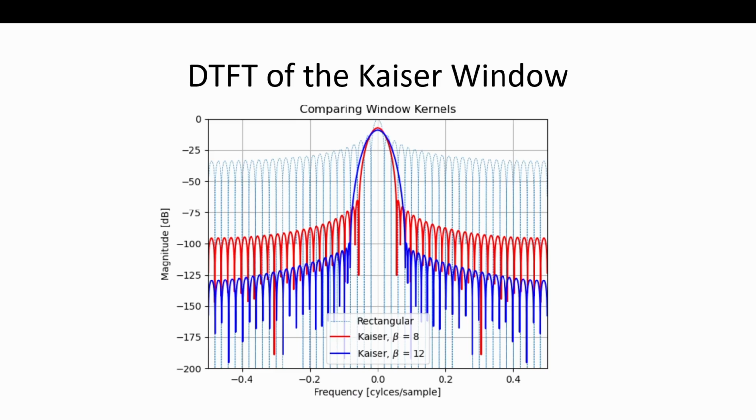So take any of these windows, and we can play with it in Python later. You'll see it. Pass it in, take the FFT, but not just the FFT. Zero pad the heck out of it, and then you'll see this result. And it's telling you everything you need to know. Pretty cool. So you can compare all the windows you want to use, and you can see what the trade is in terms of window.